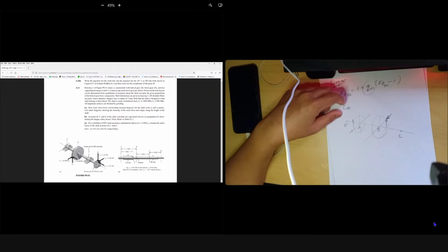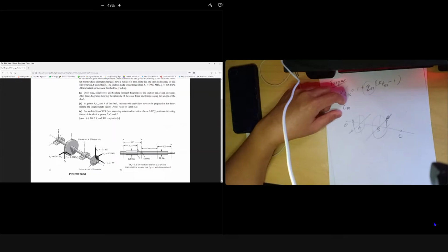If you look at the diagram, the location of shoulder E. For those who have done the assignment, actually we don't have torque at E. Can you see this shoulder E? Is this shoulder E within the torque zone or not? We have torsional stress at shoulder E. Shoulder is critical, right? We have a stress concentration factor, right? We have torque at E here.